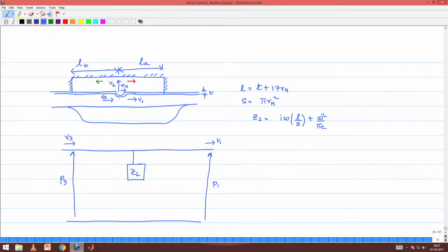But other than that there are two more bypass lines. After the sound escapes from this hole, there is again a bifurcation towards the left and the right of the chamber, right. So, again there has got to be two parallel paths for the sound to go to, and this is given by each of these impedances.